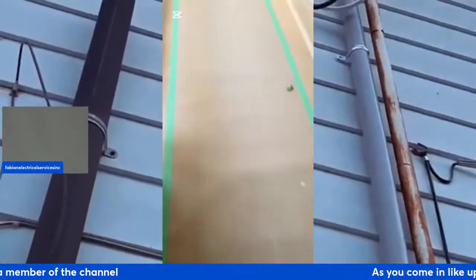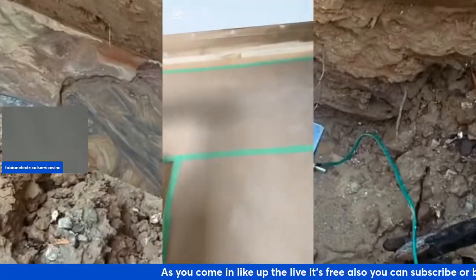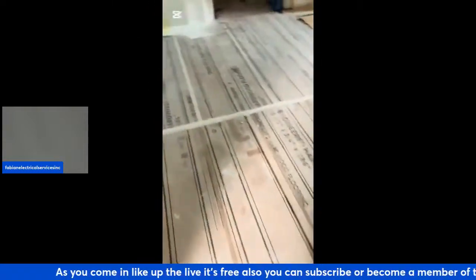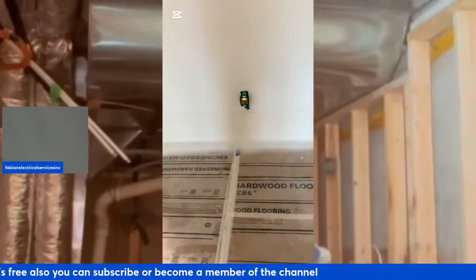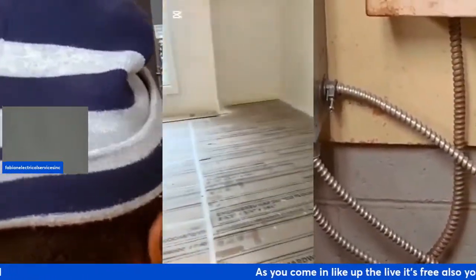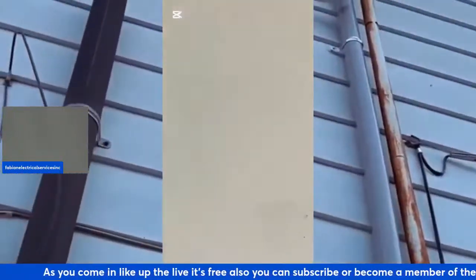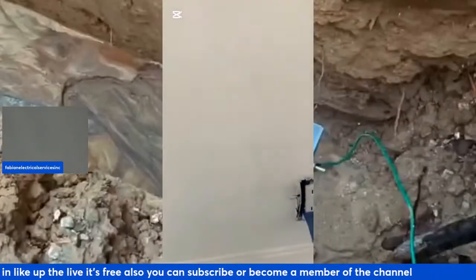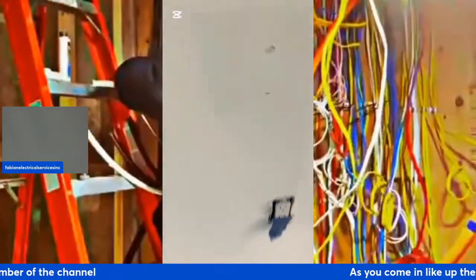It was the first time I experienced it, and the inspector brought it out to me and said I needed a GFCI there. Obviously, I never figured it is close to the water, and with the fridge never being on a GFCI before and the position it was in, the location, it called for one. Normally the fridges are not in front of the water. They're tucked away in a well-designed area, but this one wasn't. So I had to put the GFCI there.